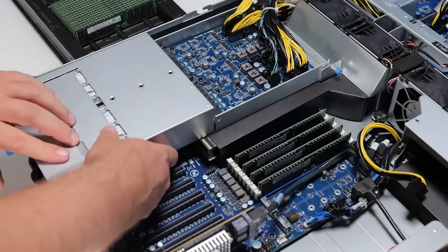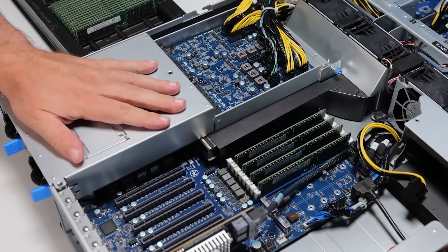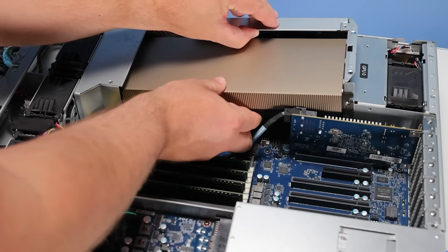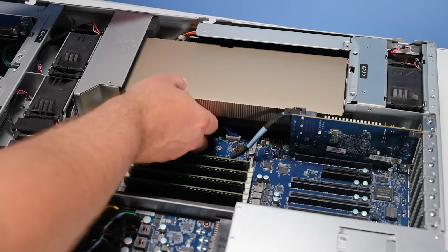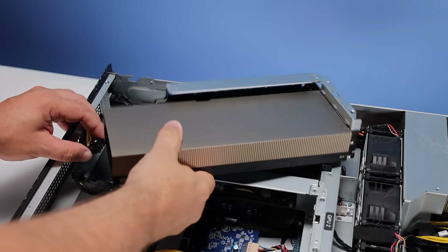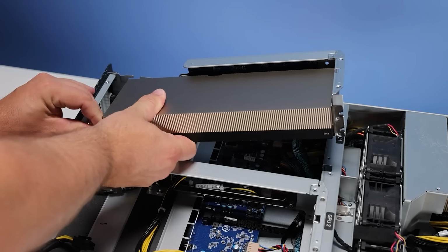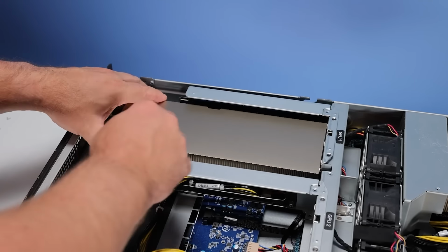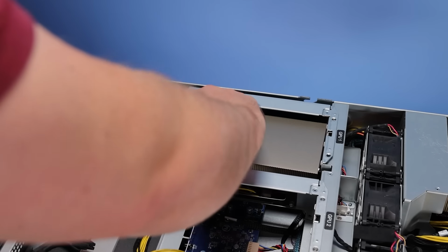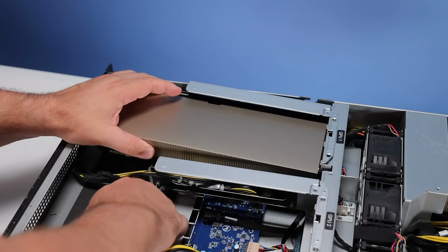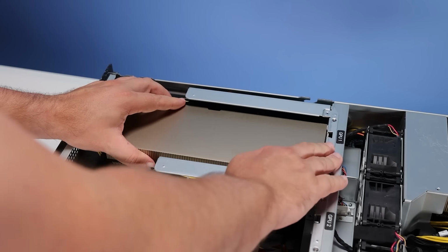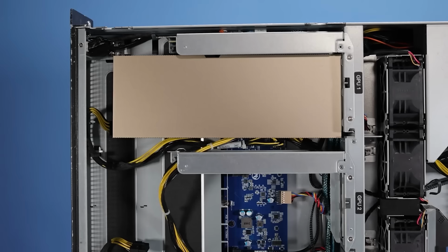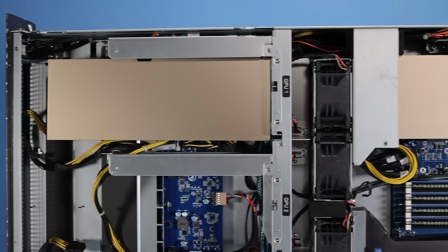And so after we installed the Ampere Altra Max processor, we were able to also install the NVIDIA A100 GPUs, which go in these GPU slots, and these are some of that really new style of GPU slot where they're cabled because PCIe Gen 4 signaling requires, in a lot of cases, cabled access. That also means that these things are fairly easy to service because you can just pop them out, and they're much easier than the old riser cards or something like that because they are on cables.